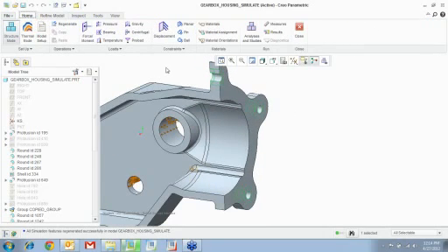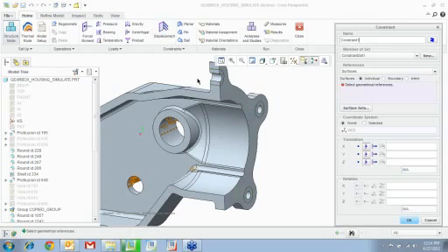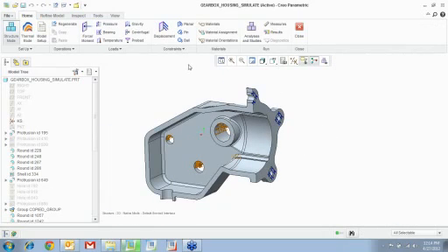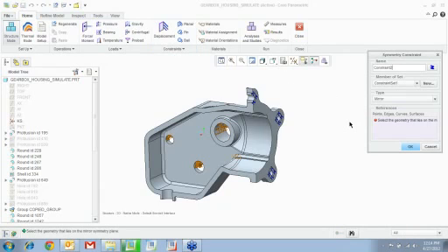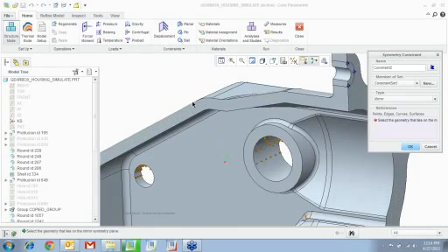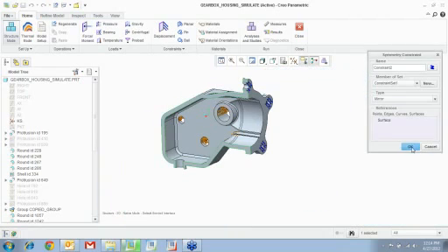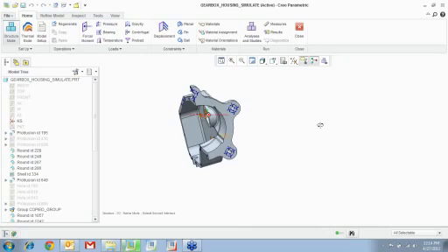Now I want to go ahead and constrain the top surface where the bolt head interacts with the part. So I'm going to fully constrain that, and I'm also going to say that this part is symmetric, so I use mirror symmetry and pick that surface. Alright?